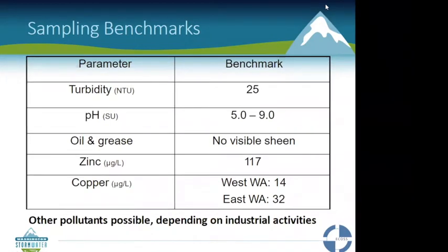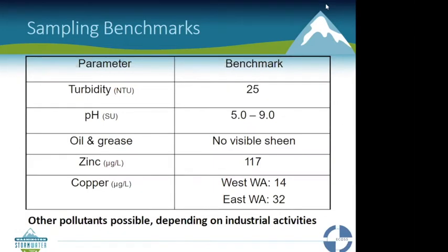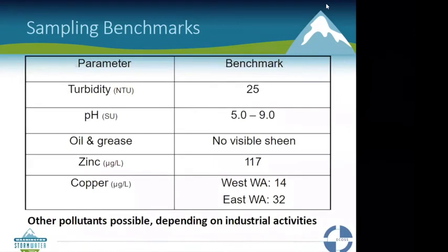So if it rains like that, like it sprinkles a little bit and then it dries out, or we have showers and then no rain for a while, the 12 hours doesn't actually start until you have a discharge from your facility. So in other words, if the stormwater hits your pavement, but there's no discharge from where your sampling point is, if the water is not leaving your site, that is when the 12 hours start. I hope that makes sense. Are there any other questions about that? I know that's a little bit tricky.